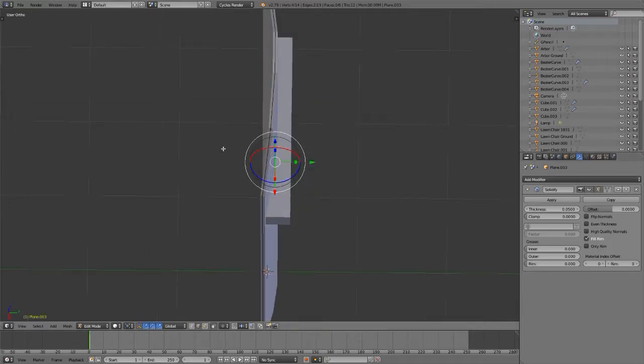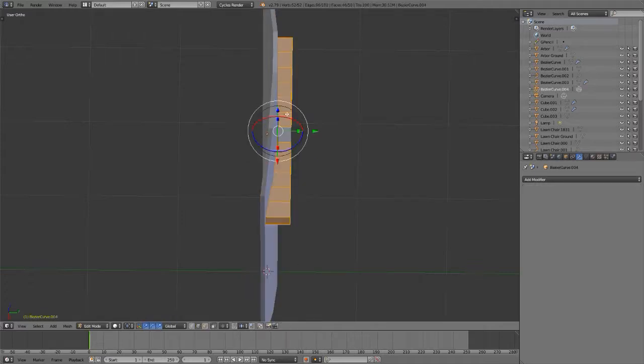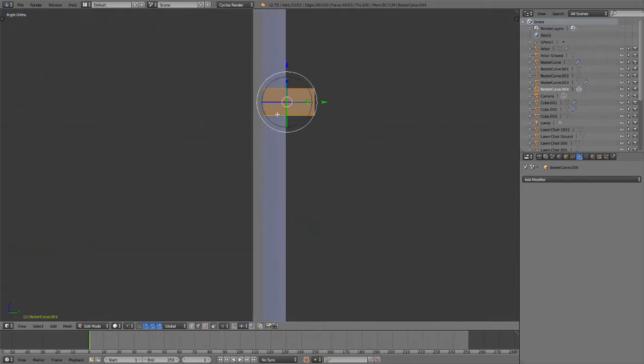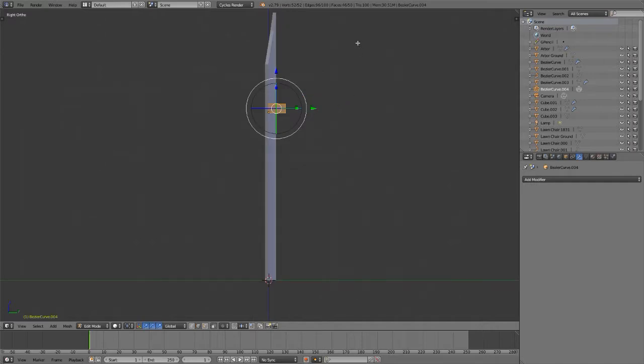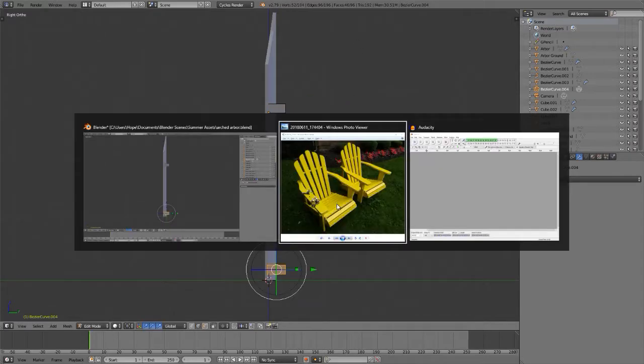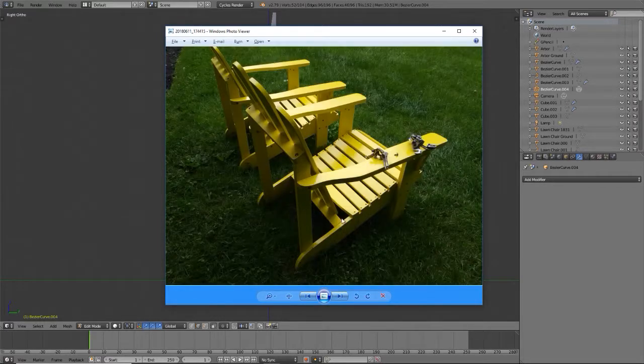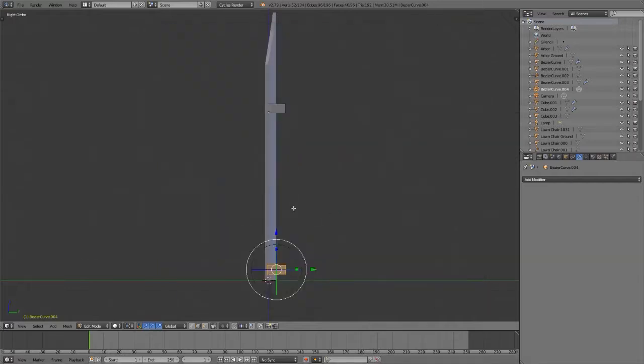And before I do anything else, I'm going to tab into object mode, tab into edit mode for this brace, hit 3 on the number pad to look at it from the side. I'm going to make a copy, bring it down almost to the bottom. So I want to take everything, which is now everything, Shift D, Z. Bring it down almost to the bottom because there is another down at the bottom, but its curve is closer. You're going to see it right now.